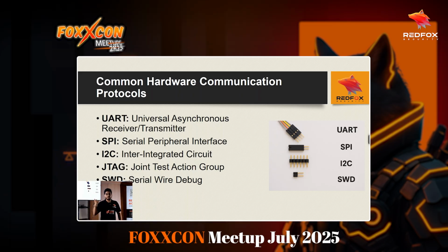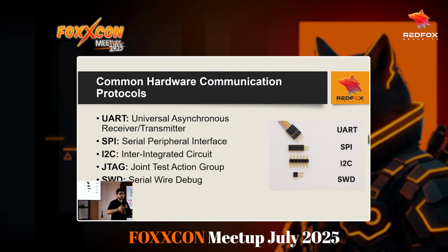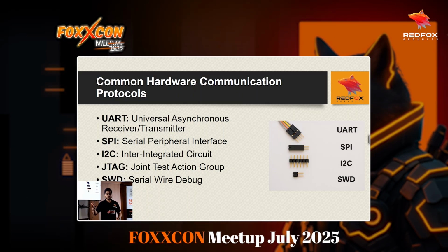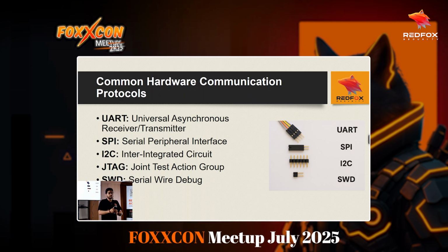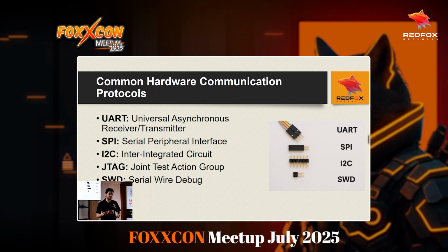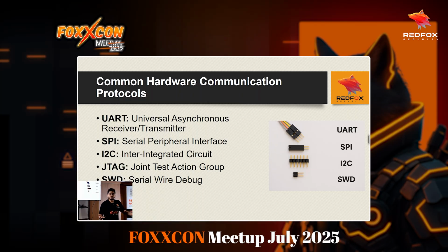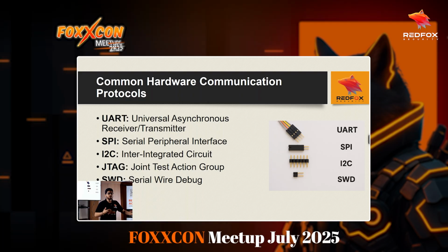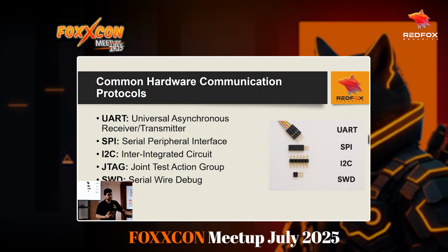Here it is serial. It's the same thing. You connect it with cables to your computer, and it'll give you the output of the device on your computer. The logs, maybe, depending on how the system has been designed. That is what is going to display. So what companies do while developing the device is use this to debug it, to see what's going on, to see the logs, if there are any errors, things like that.